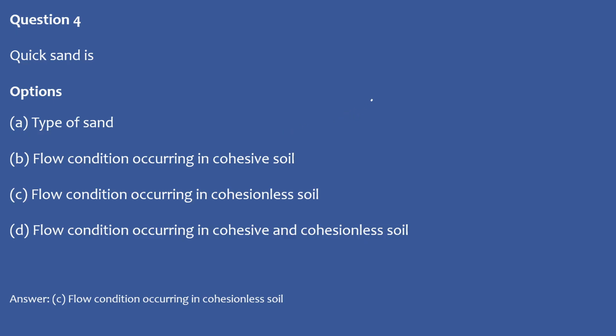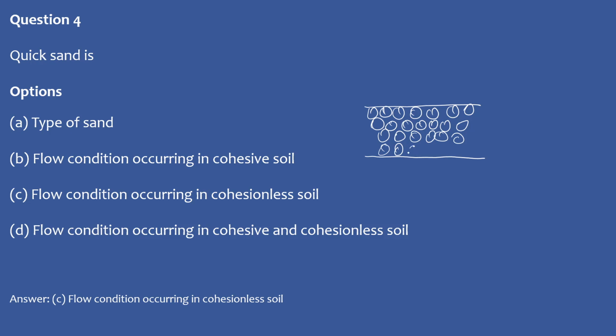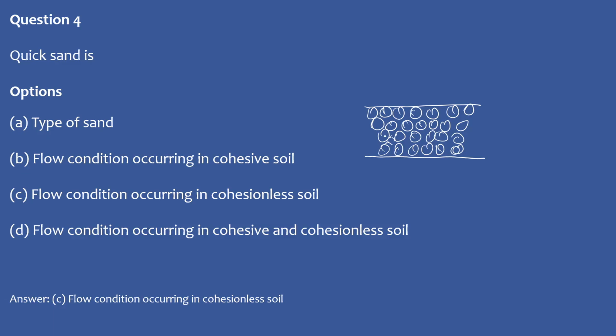Usually in your soil matrix, there are some soil particles along with some voids, and in those voids you can have the air as well as the water available. At a certain condition, the pressure applied by the water, which is also known as the pore water pressure, becomes equal to the load coming to that point.